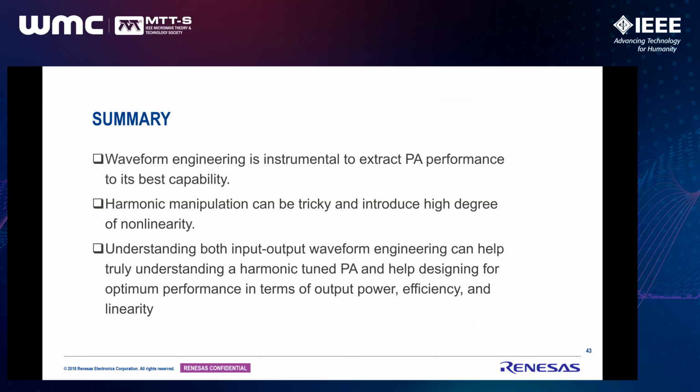Waveform engineering is definitely instrumental to extract the best PA performance, but it also becomes tricky because there are bad regions in terms of harmonic terminations as well as good ones. Not only that, it also involves iterative terminations in terms of fundamental and harmonics.